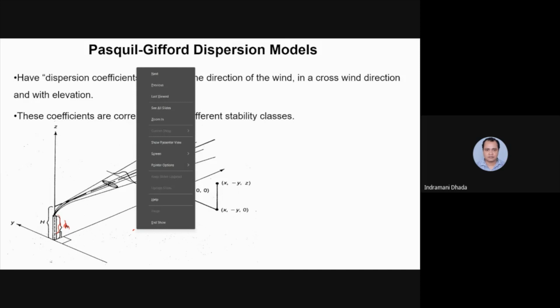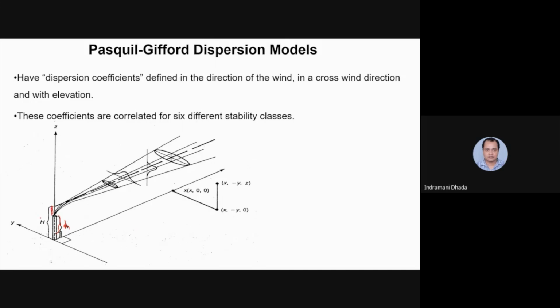This side is called plume rise. This side is called plume. Why plume rise? Because inside the chimney the temperature is different. When the gases come out, the surroundings are at atmospheric temperature and atmospheric pressure. So whatever the plume releases will suddenly go up, until its pressure and temperature become the same as the atmosphere, and then only it starts spreading.